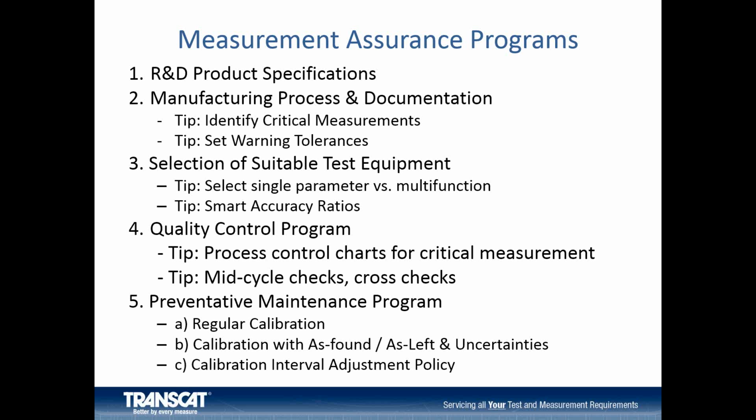That was their process tolerance. Well, they in turn set warning points of plus or minus 5 degrees. And from the warning point, they selected test equipment to monitor that 4 times better. So they had test equipment that was plus or minus 1 degree. And then they selected a cal provider who could provide a calibration 4 times better than that. So plus or minus 0.25 degrees.